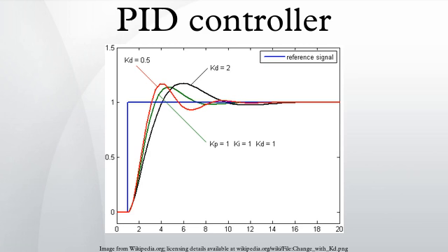Stability. If the PID controller parameters are chosen incorrectly, the controlled process input can be unstable, that is, its output diverges, with or without oscillation, and is limited only by saturation or mechanical breakage. Instability is caused by excess gain, particularly in the presence of significant lag. Generally, stabilization of response is required and the process must not oscillate for any combination of process conditions and set points, though sometimes marginal stability is acceptable or desired.